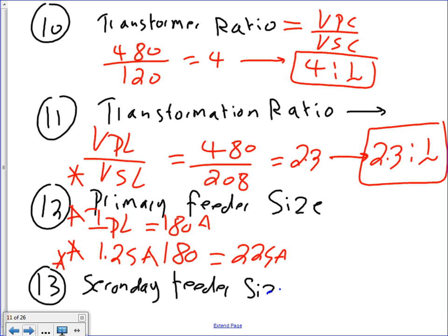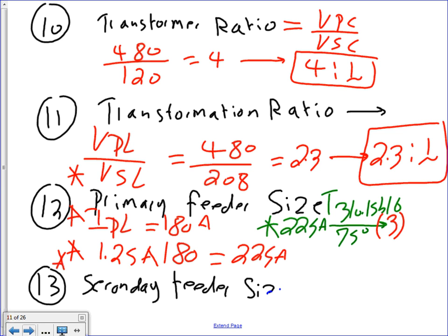225 amps, thank you. The last step is you're going to take the 225 amps to 310.15(B)(16). Remember that table under the 75-degree column? I need you to go there and size it for me, please. How many conductors first? It's going to be 3 conductors. Each one of them is what?